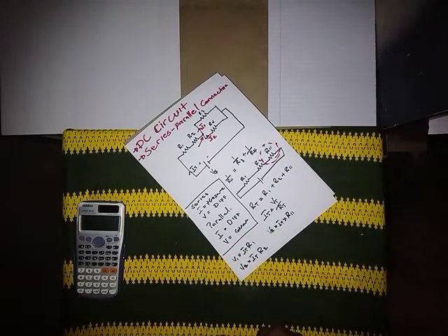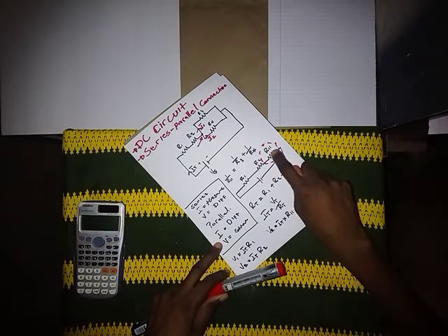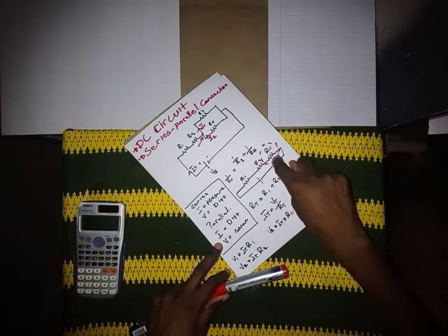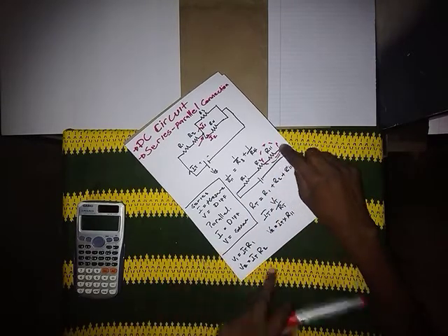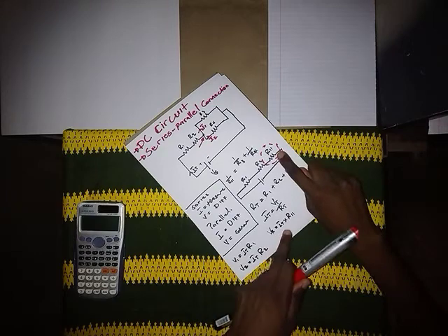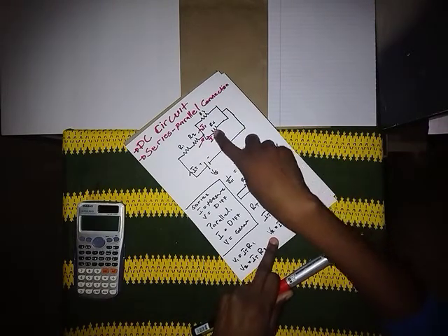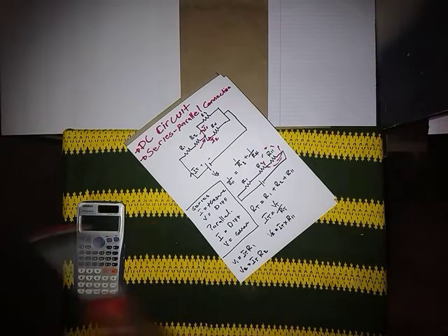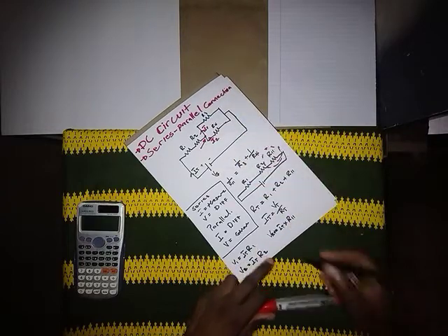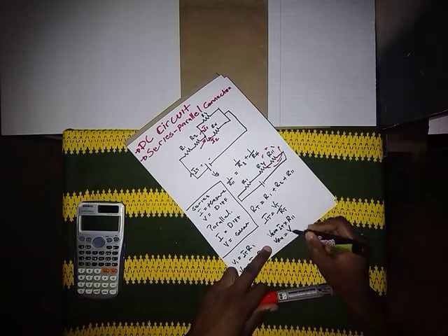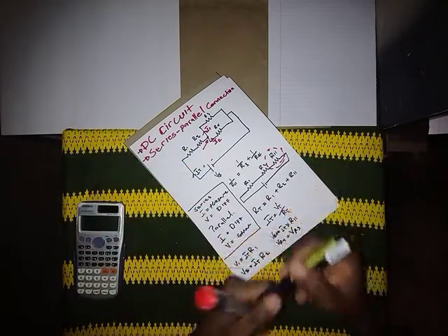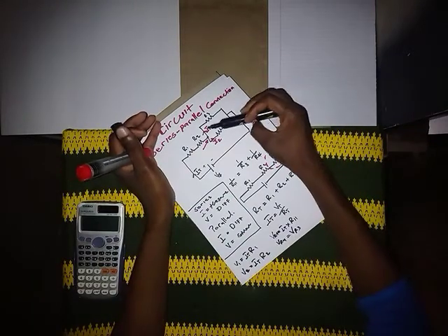We come back here, because now they are in series. So if this is in series with R1 and R2, that means the current that is passing here is the same current passing through the parallel combination. So if we use the value of the parallel resistor, we can use the IT and the parallel resistance to calculate the voltage through here, because after getting the voltage of R4, we know VR4 is the same as VR3, because they are parallel.